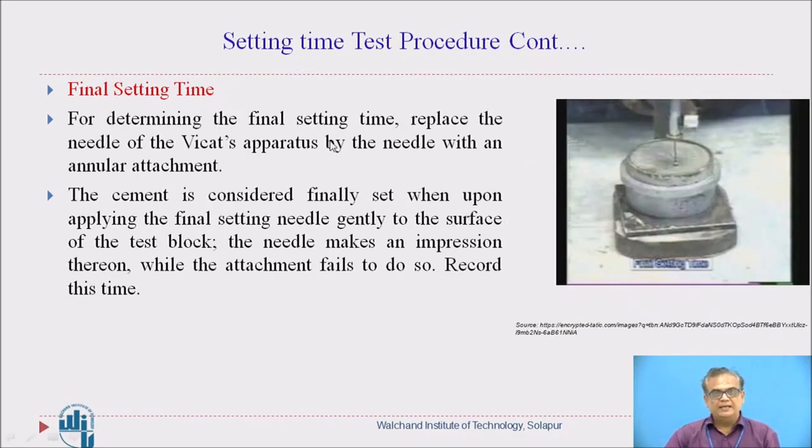Now let us see the final setting time test. For determining the final setting time, what is done? This needle is replaced with the final setting time needle, right? And this needle has a pointed needle at the center and an annular attachment around it.